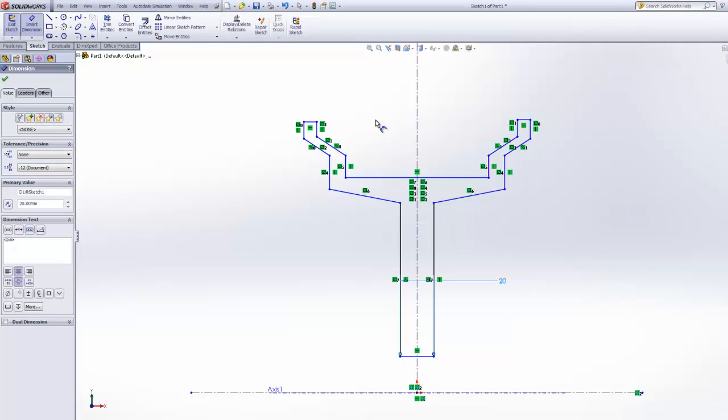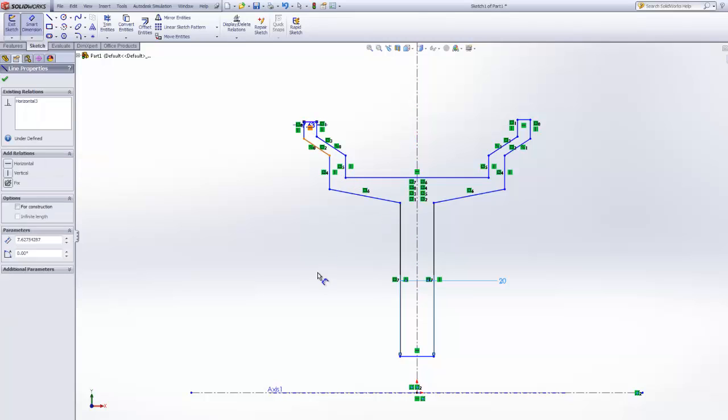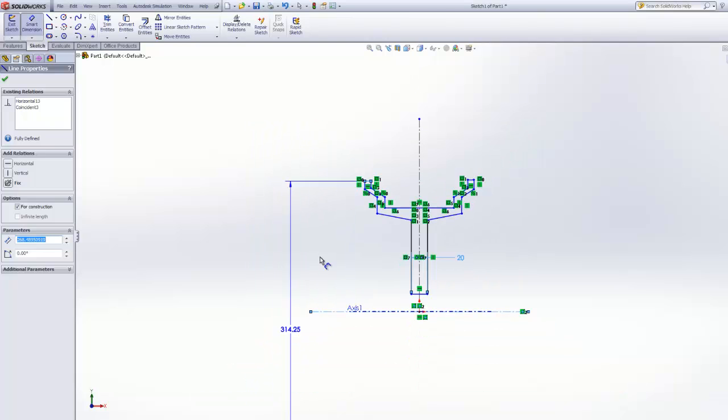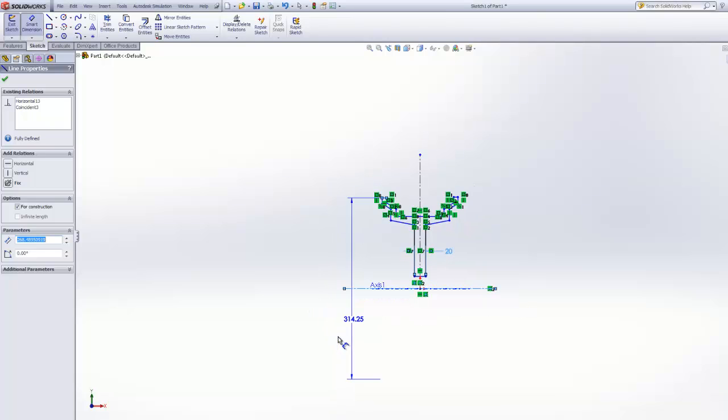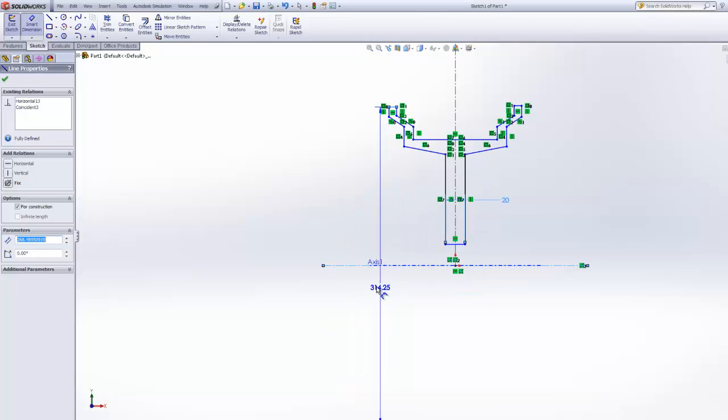Everything seemed to pull together there, and measure the outside. Now watch this. I want to measure using diameters. I can go here, and that gives me a radius. If I go on the other side, notice how that turns into a diameter. Radius, diameter. I'll show you how. If I put it up here, it's a radius. If I bring it down here, it knows to go on either side of the axis, and it becomes a diameter.